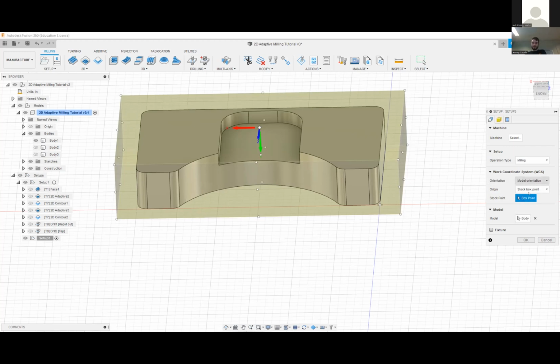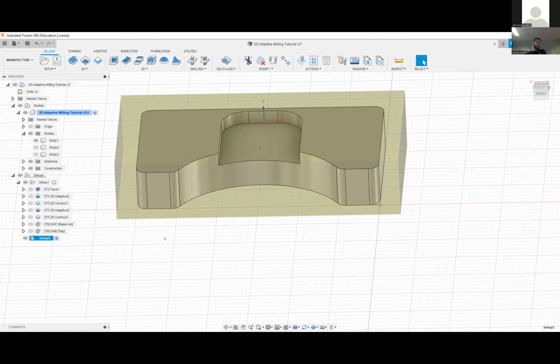Yes. So it's the same 3 things for all these geometries, right? It's somewhat simple, but the big secret is like, okay, I've got a complex part. I just have to do this like 5-10 times for some weird features. So there's no way to just do it all over. Flip it over. Yeah, so there's fancy ways of getting rid of it with a 5-axis machine. Like sometimes you can flip it sideways and go back and forth on the back side of it. It doesn't work well. You'll have to flip it over.